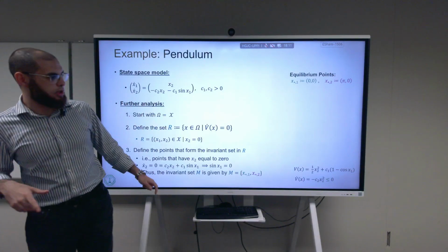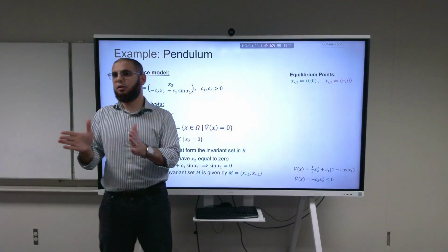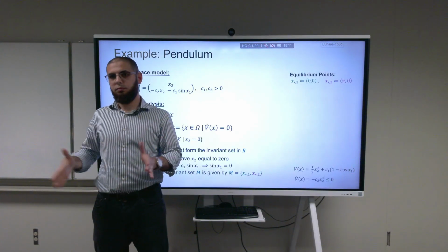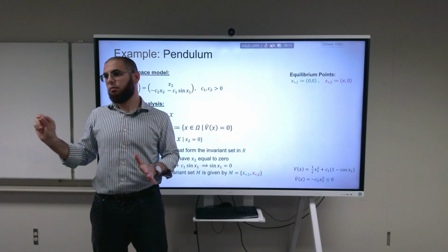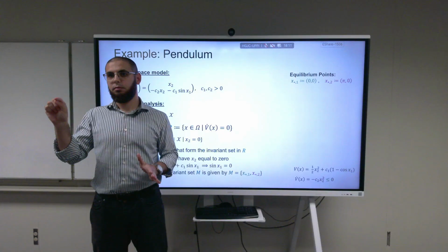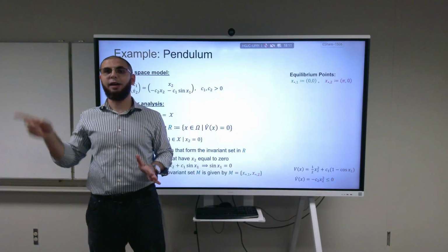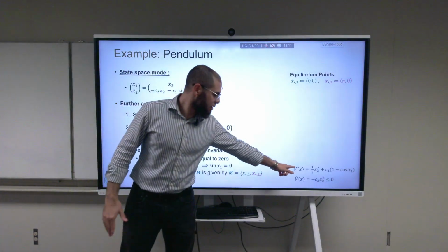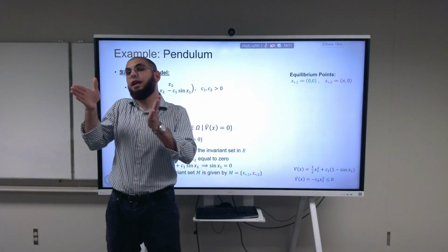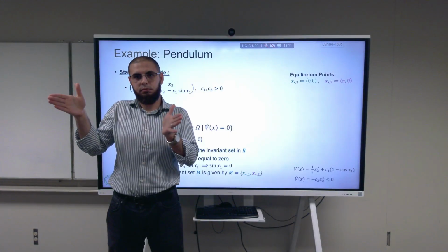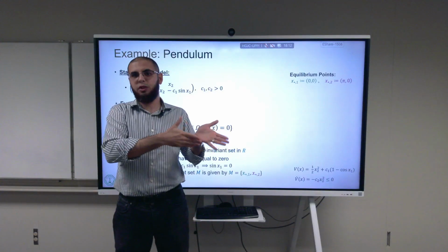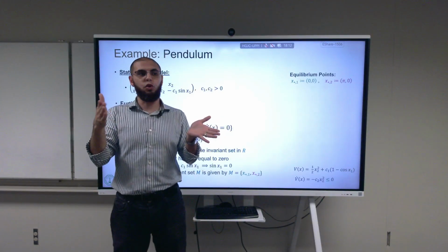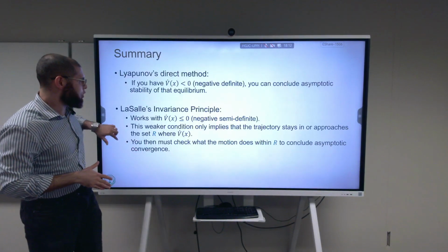Take a look at the Lyapunov function that you chose, V of x. Remember, what are the values that we found? It was going from 0 to 2. It is 2 exactly at x1 equal to pi. And when I included V of x less than or equal to 2 in the x1 direction, then we included that point. What should we do to restrict it? Remove the 2.